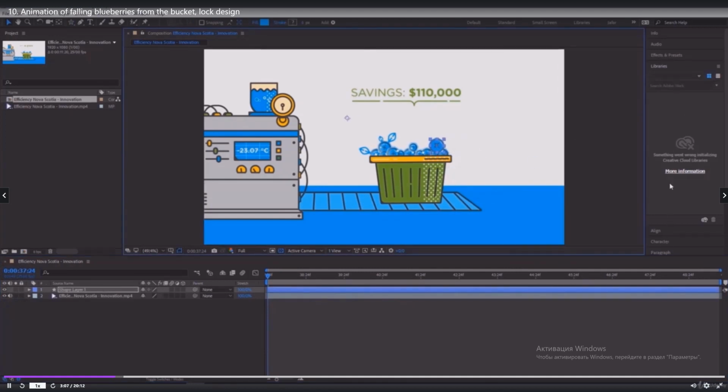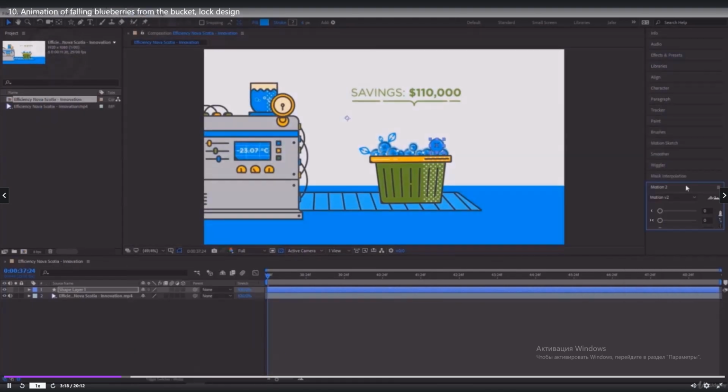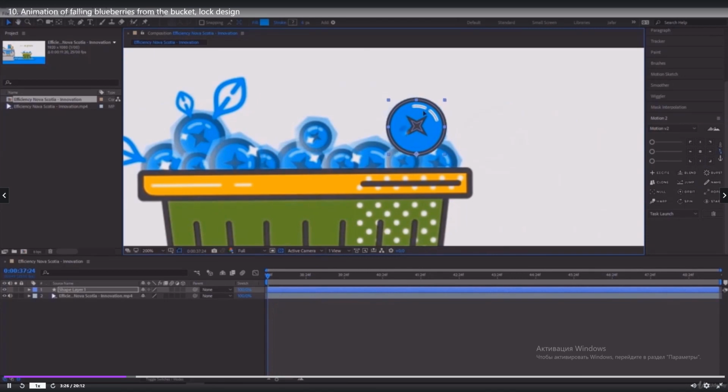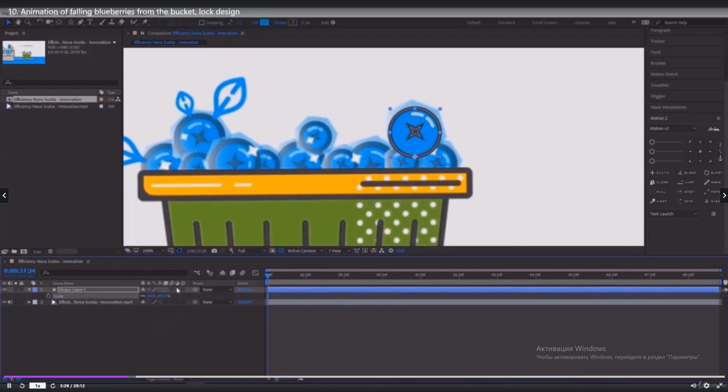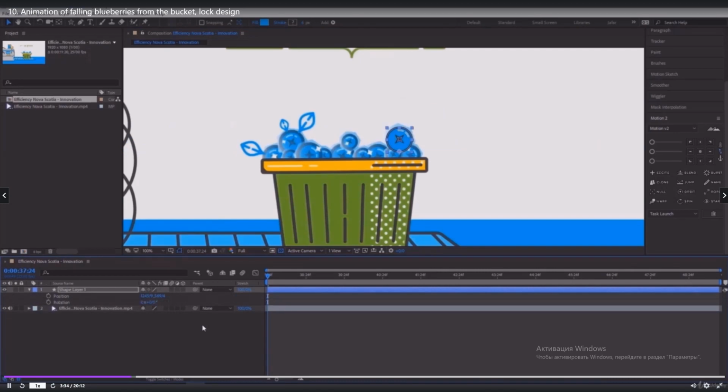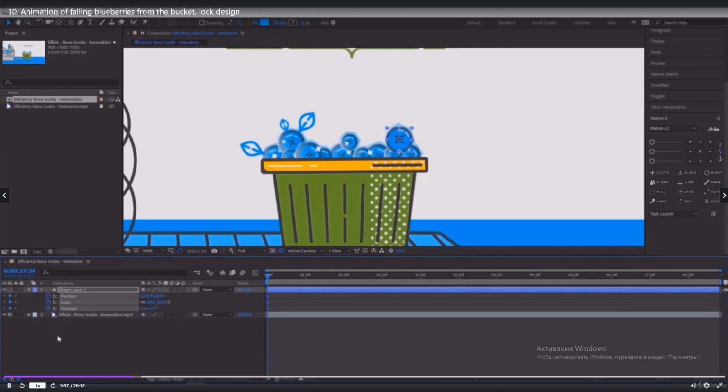Set its anchor point under it. Why would we do that? Because we're gonna use the squash and stretch. Open the Motion Tools script. Set its anchor point beneath it. Then move it here and then reduce its size a little. We start now. You need to animate its position, rotation, and scale. Add keyframes to all of them. Since we have both vertical and horizontal movements here, and since they have different movesets, it's best if we separated the position parameters.